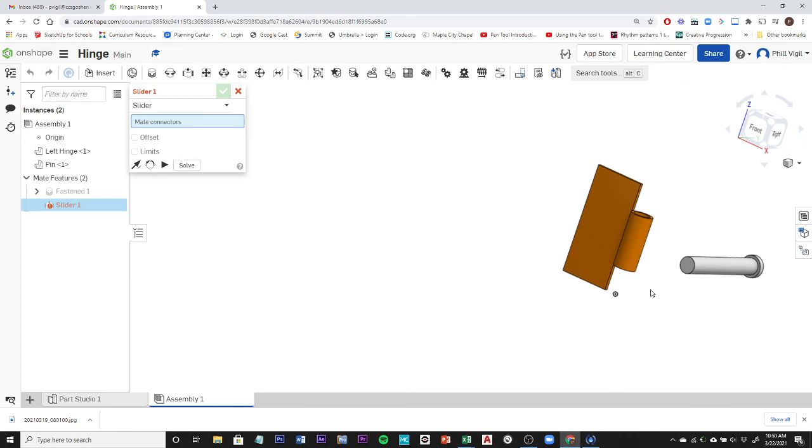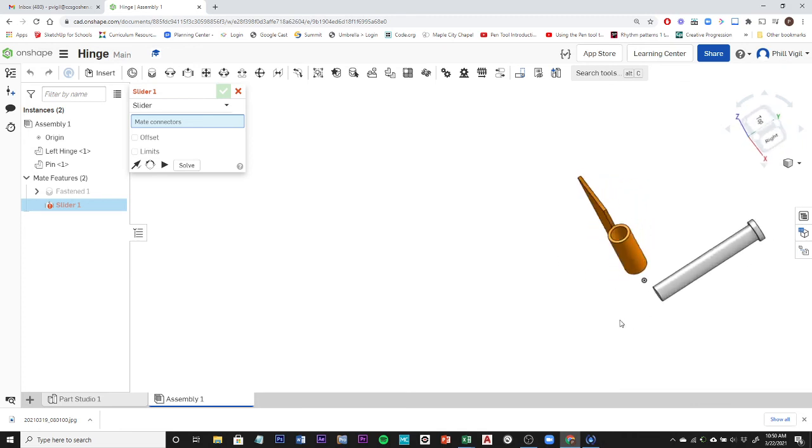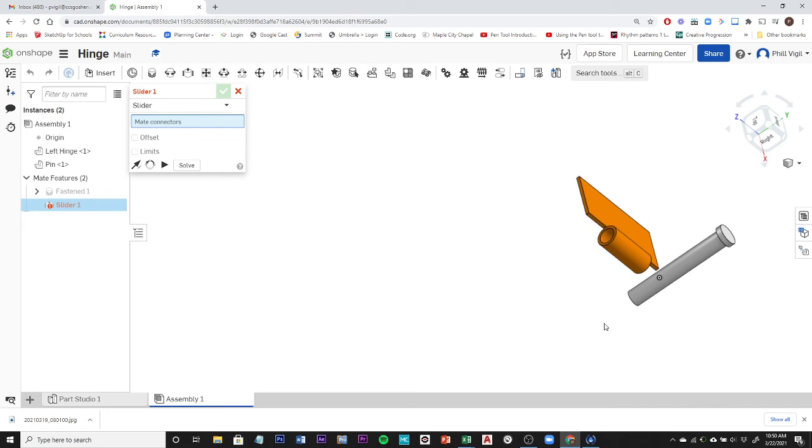And I want this to be oriented in the right direction, so this is a little tricky. So I want it to be up and down with the Z pointed up. So I could use this and then offset it, but I want to use the bottom to attach it. So if you reference the top, it's going to align the Z in the correct position.